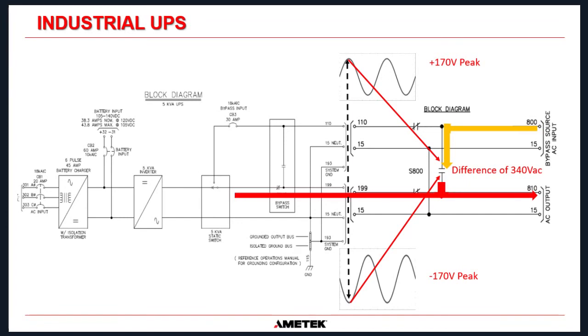So always follow the procedure on the front of your UPS when you're transferring from normal to bypass. Because near enough every UPS manufacturer will tell you the first thing that you have to do before you move the manual bypass switch is to transfer the system to static bypass by pressing the button on the front of the system. What that does is the output of the UPS then will be exactly the same as the bypass. So the voltage difference across that contact will always be exactly the same. It will be a 0 volt difference across that contact, and therefore you can move to bypass safely.